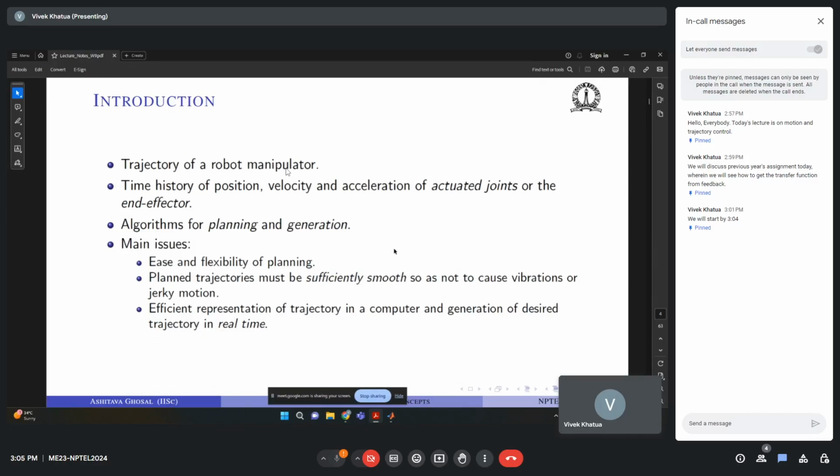All of these would boil down to where the end effector is at a given point in time. Based on that, you would get your joint position, velocity, and acceleration. Then there are other terms also: jerk and snap. They are higher order derivatives of acceleration.